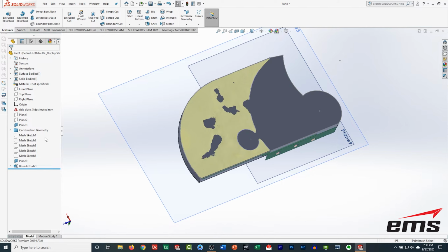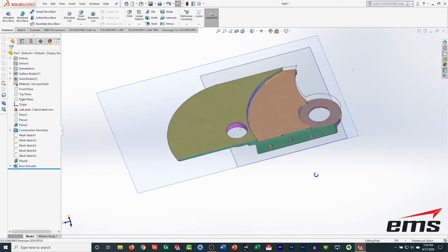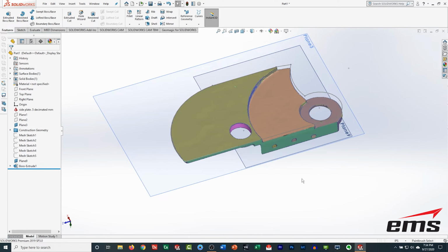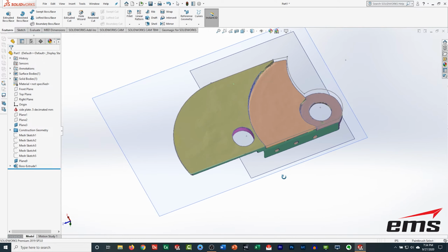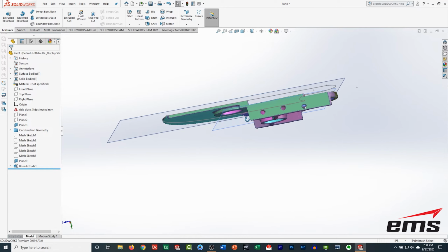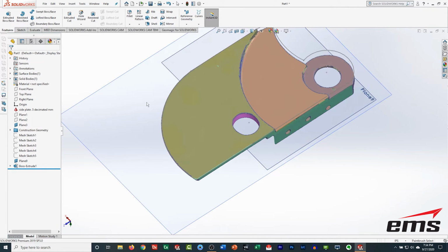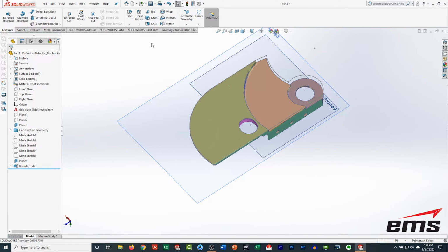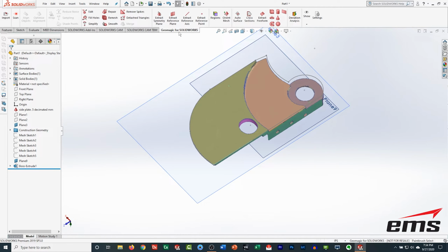And again, you can see where you've got gray, but then you can see the scan data. So that tells you this part is not flat. And you can see it in the scan data. You can see this is a casting. They're never perfect. They're typically machined, so they're usually cast and then machined. So they'll have machined surfaces. But it's not uncommon when we start fitting perfect geometry through a casting that you're going to see differences.